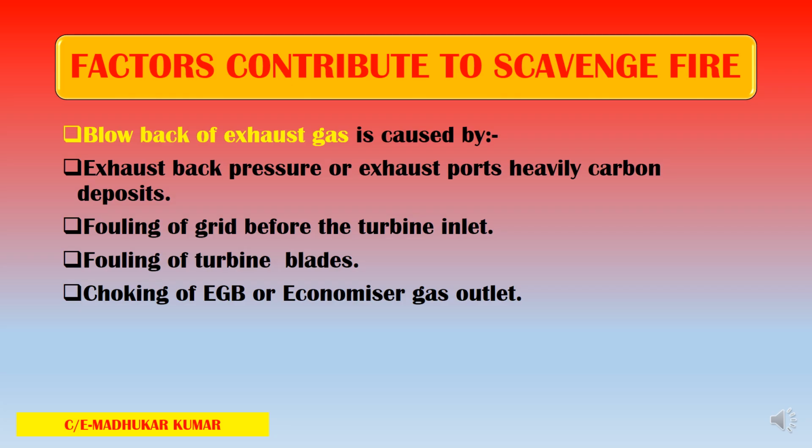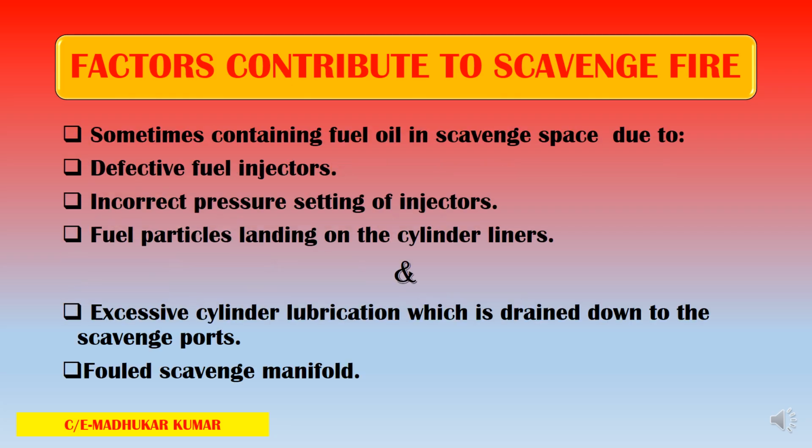Choking of the EGB or economizer gas outlet is also one of the main causes of the blowback. And then this creates a back pressure, which is one of the causes of scavenge fire.